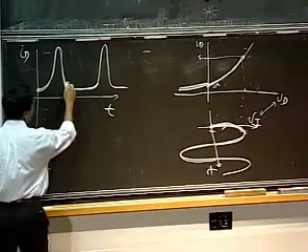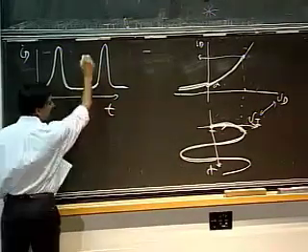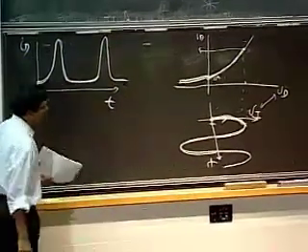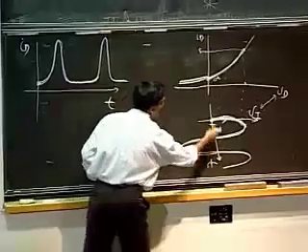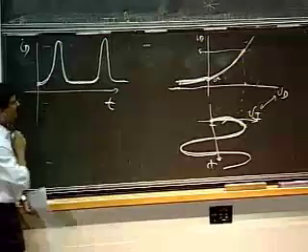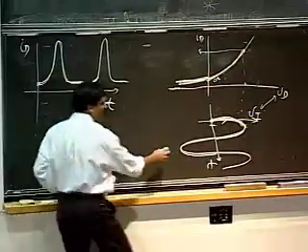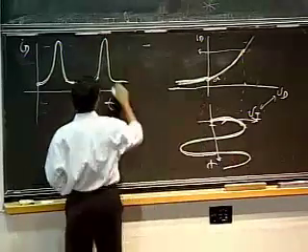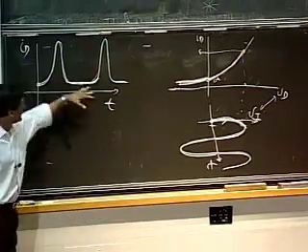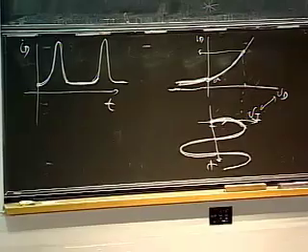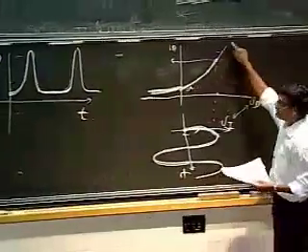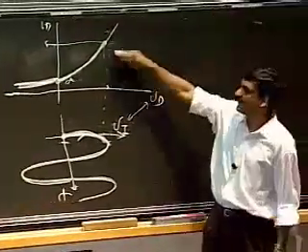Okay, what it's done is that rather than giving me a nice little negative spike excursion here, what this is doing is that it's taking this excursion and simply slamming it down to this value here. Okay, and then again, when I go back up, I get this peak here. So notice that what was a nice little sinusoid out there gets hammered and squished into this funny curve here. Okay, what this device is doing is for positive values, it tends to produce exponentially greater current.